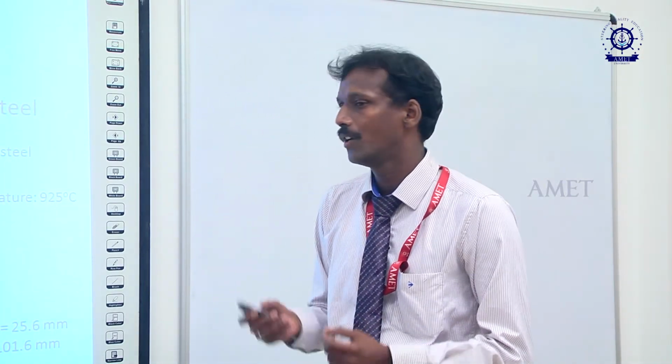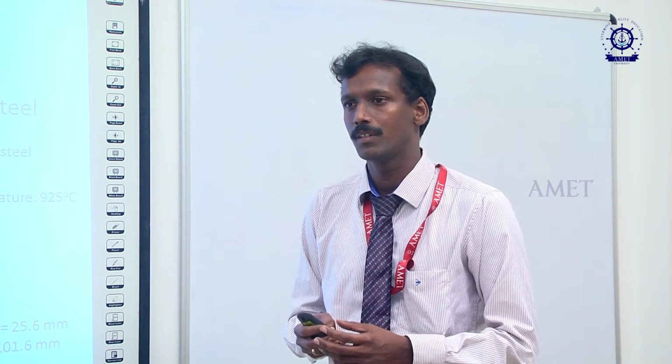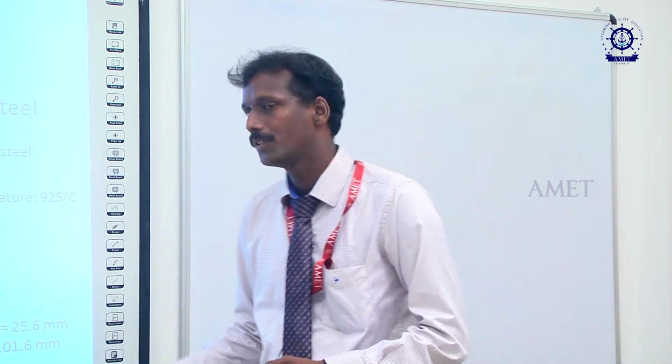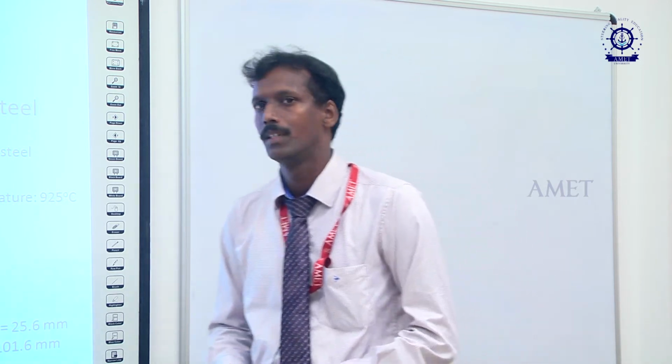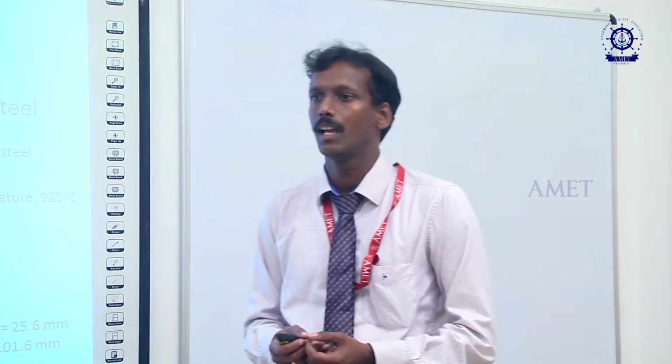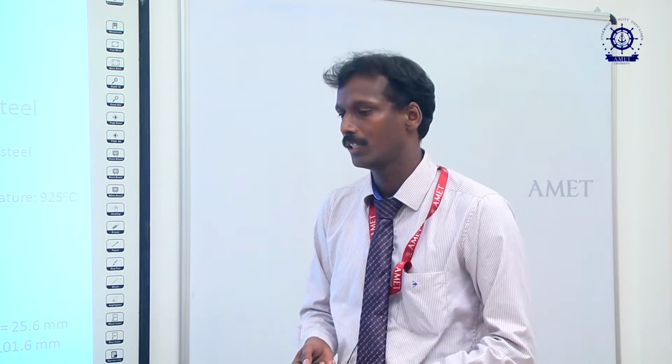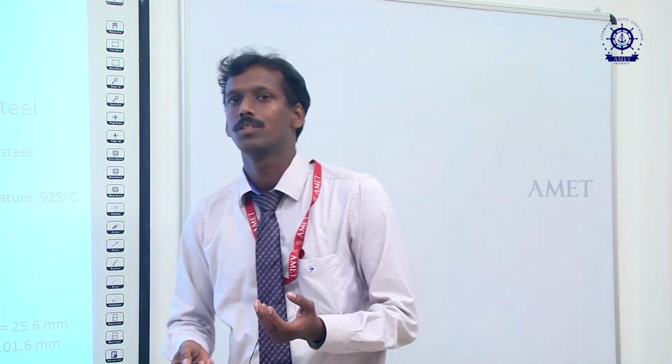First, you have to prepare the specimen with a diameter of 25.4 mm and a length of 102 mm. For example, we can take 1018 steel.